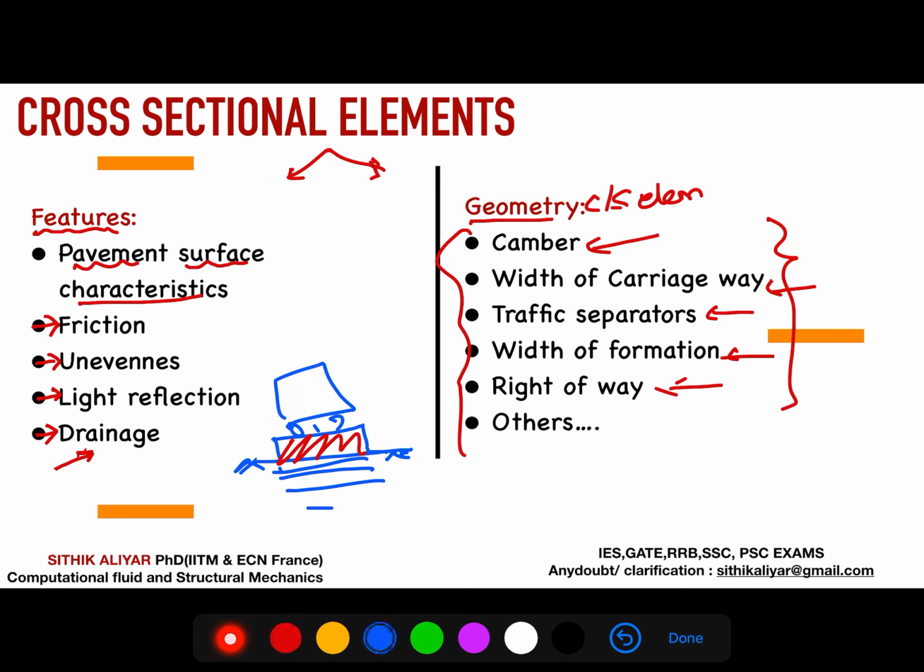So how will it drain quickly? Consider the road should have a perfect side drain. Okay, so consider this is the pavement. When the water or rain falls, the water should drain quickly to the side drain and the water should not penetrate. The pavement surface should be able to reflect the water, and it should be closed at the top so that it won't absorb the water.